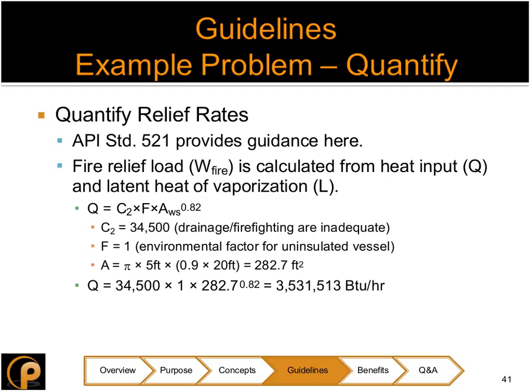Okay, thank you. What maintenance should we do on PSV and PSE? I think we sort of talked about this earlier, especially with PSVs. With PSEs, which is a term that can imply rupture discs, one of the maintenance items you may want to do is replace it every so often. You could also look to the manufacturer for any of their maintenance activities that they think would be best suited for your application.